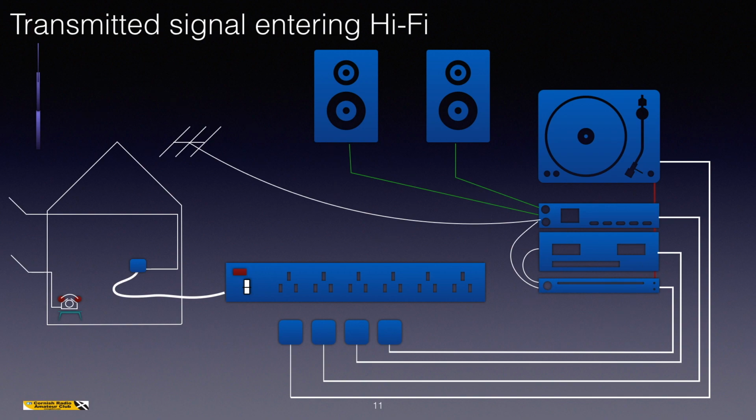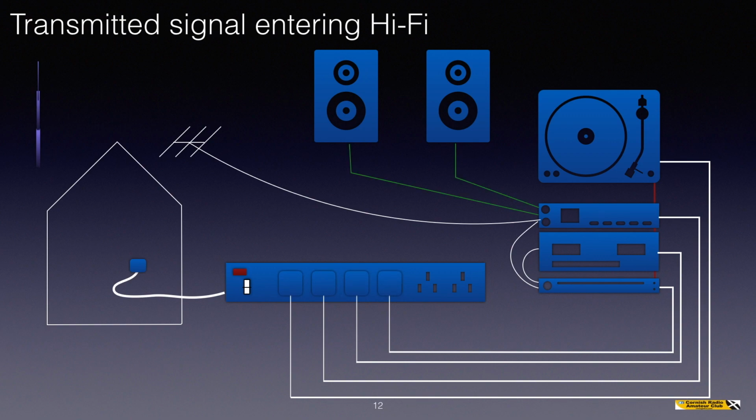And here again you can see the signal being radiated. This time we've added some phono leads, or some small signal leads, between the various components. That's carrying the low-level audio signals between tape decks perhaps and the amplifier and the tuner. Once again, signals may enter these phono leads, be amplified, and then cause interference as noise on the speakers. So when we plug in our hi-fi components, where we have mains-borne interference, that is carried into the hi-fi components. So let's have a look at those mechanisms.